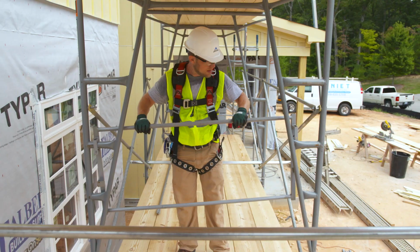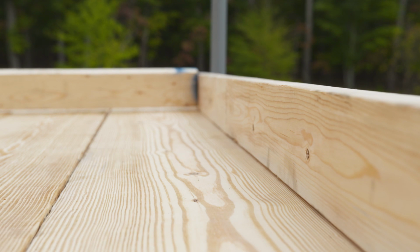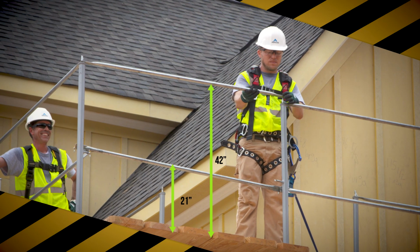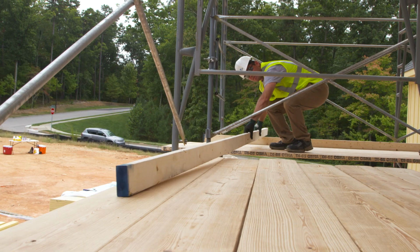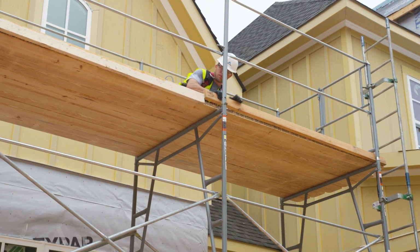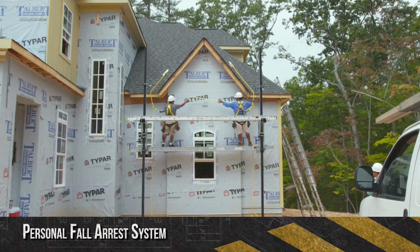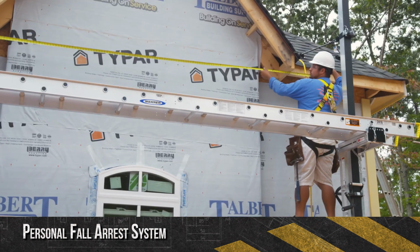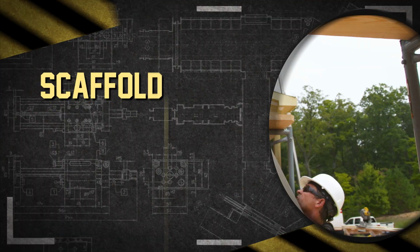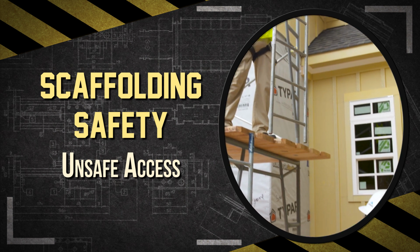must have a complete guardrail system with toe boards covering all exposed sides and ends. The top rail must be 42 inches high, the mid-rail 21 inches high, and the toe board must be at least 3.5 inches high, or as high as the material on the scaffold, to prevent objects from falling off. If guardrails can't be used, workers must use a personal fall arrest system when the scaffold height is over 10 feet.